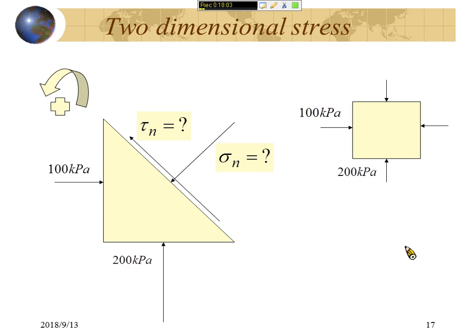So you can multiply the normal stress times the acting area. Then you will have the forces. You have 2 forces and 2 equations. One is the force along the x direction equals 0. And the other equation is the force acting in the vertical direction equals 0. Then you have 2 equations and 2 unknowns. One is the normal stress and the other is the shear stress. So you can solve the normal stress and shear stress very quickly without any difficulties.